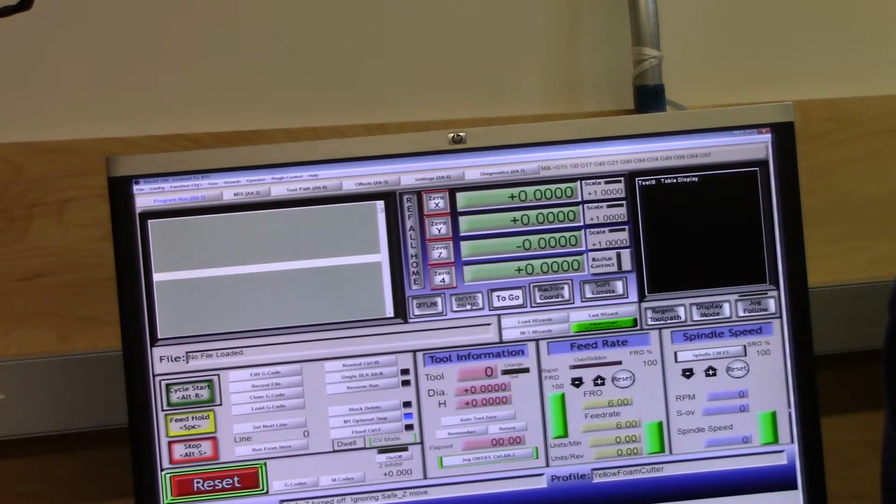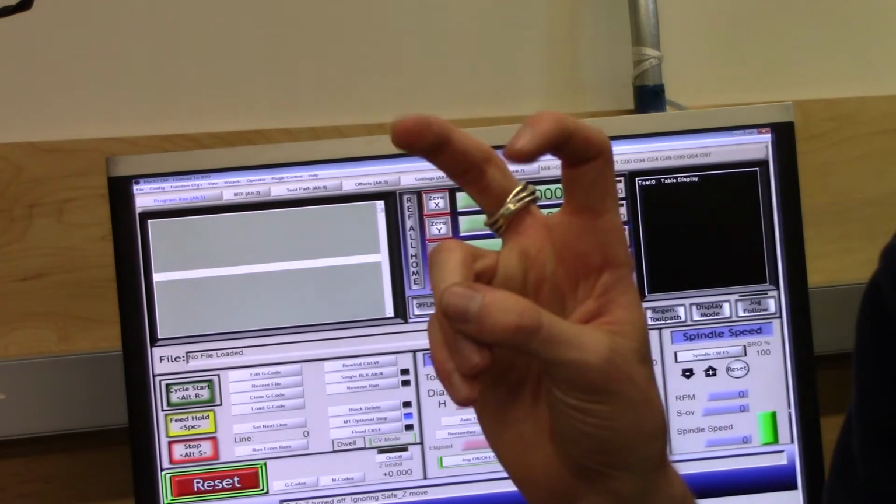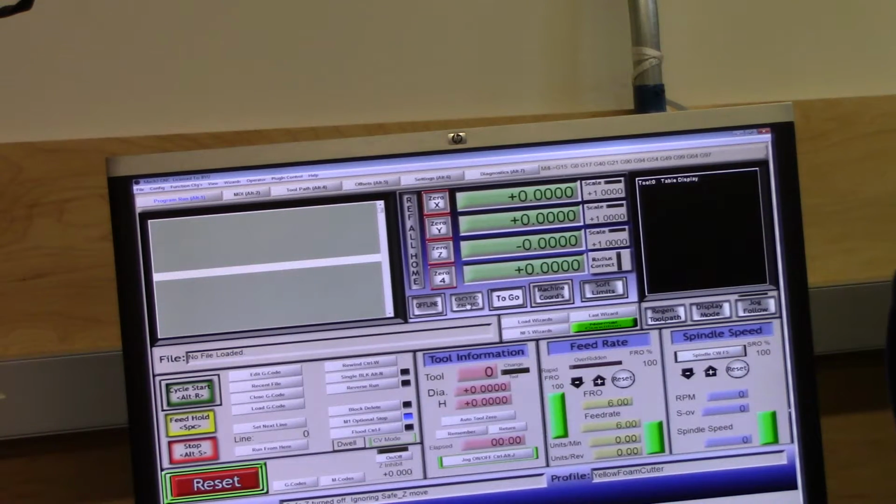So what it does is it moves the first 3 axes, X, Y, Z, before it moves the other X and Y for the other carriage. And so typically when you're going back to 0, it's best practice to use the arrow keys to get as close to 0 as you can, and then click Go to 0 to let it do the fine-tune adjustments on its own. Otherwise you might overstrain that last axis that it doesn't move until after moving the first 3 axes.